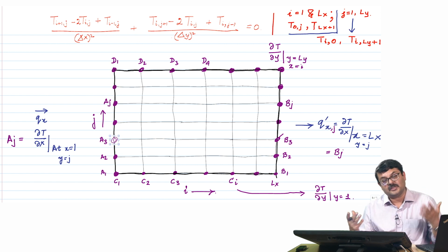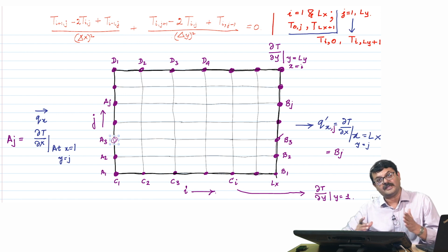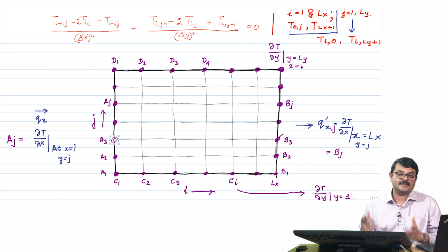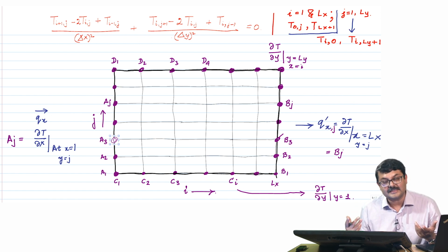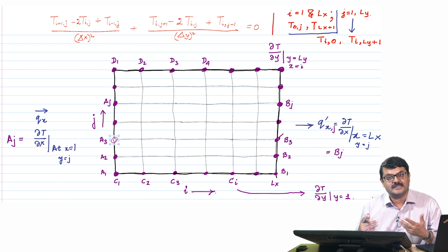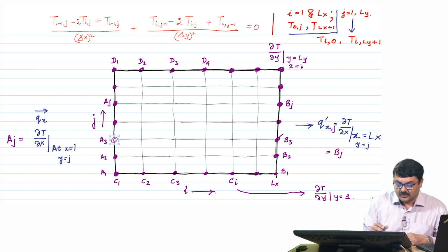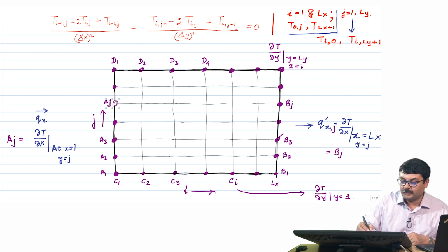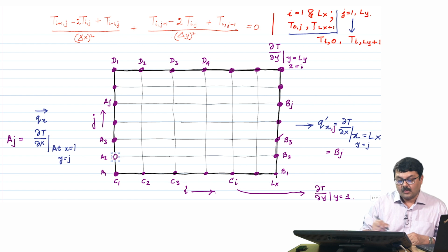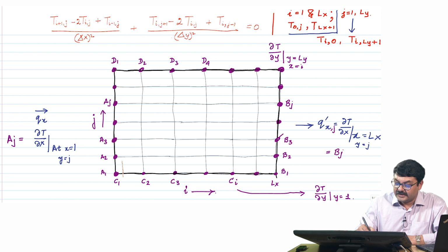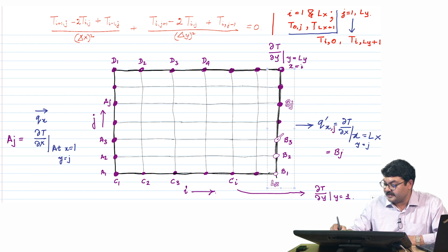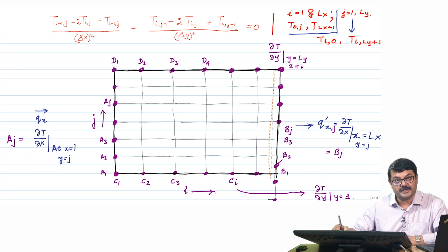So, you are specifying the amount of heat input and heat output along the boundaries, and the temperature will evolve as per the solution of the Laplacian equation given the certain boundary conditions, and you are solving exactly for that. So, what is specified at each point here, here and here and here are the values of the heat current coming in. The simplest case will be that the heat coming in would be uniform along this boundary, and the heat going out would be uniform along this boundary.